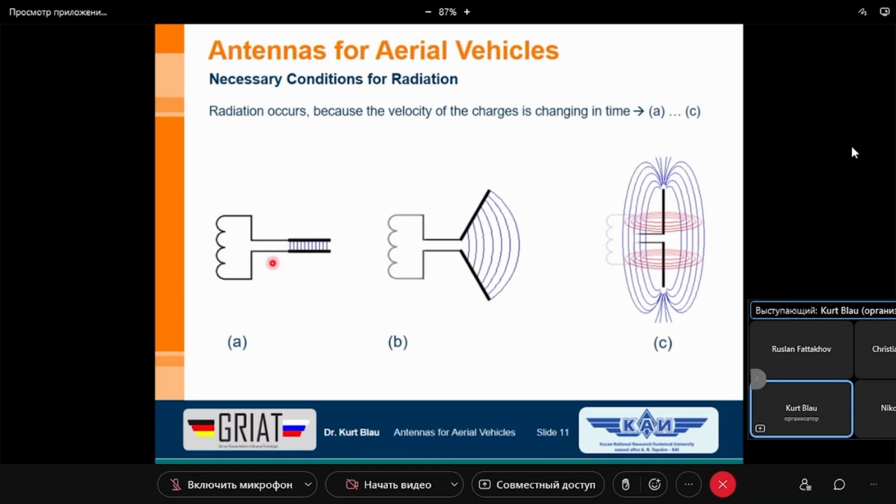Then it's clear that in this moment we have an oscillation. It's not visible here, I only want to mention this because in this moment I connect the inductance. Then we have a certain capacitance and a certain inductance, and it's clear we have a resonance circuit. The oscillation occurs only at the moment I connect the coil or the inductance to this charged capacitor. We have no external source, no external sinusoidal generator, nothing. It is only charged by applying the voltage from a DC source, and then we can connect it.